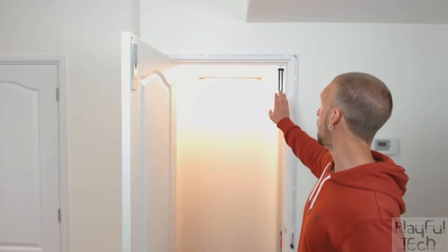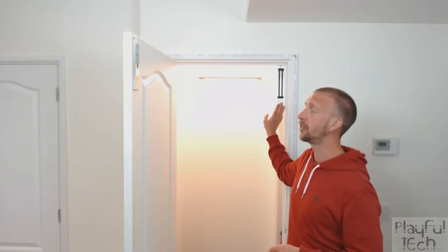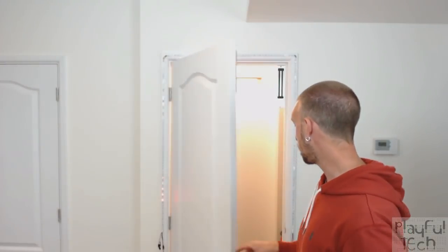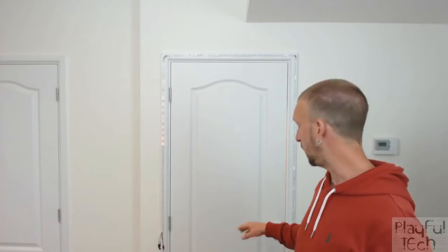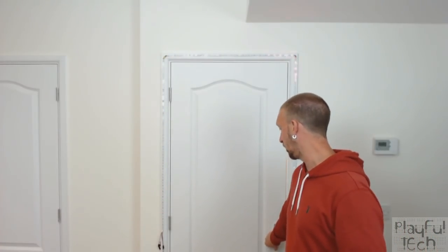The door has got a 12-volt maglock here secured into the frame, and on the other part of the door here I've got the iron bar that goes with it. If I close the door, the system is currently activated. That is secured shut, and you can see I've got red LED chaser lights going around the outside to show that the door is locked.